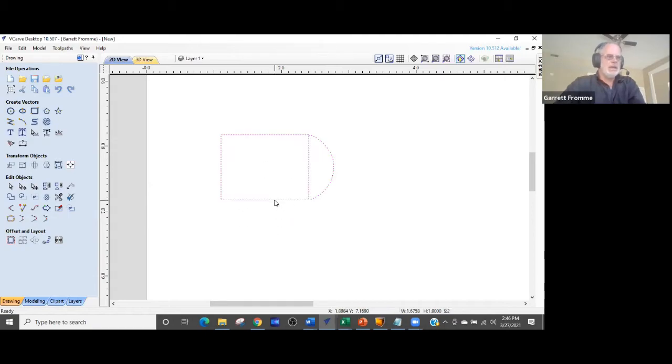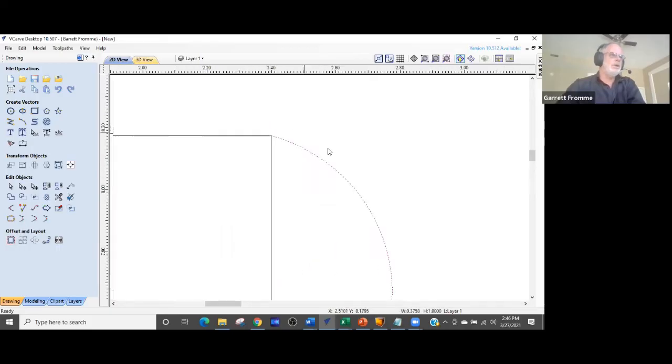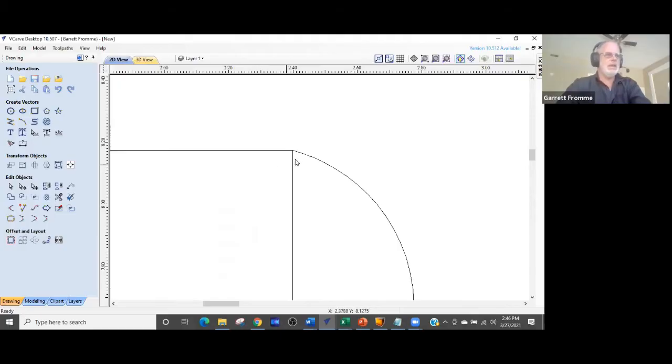Now, if I select the box and I try to merge them by using the close join the vectors, and I click it a couple times, let me just hover over that. It did not do it. What you have to do is because there's multiple lines coming into one node right now, it can't join those vectors like that. It has to be able to join one line to the other.